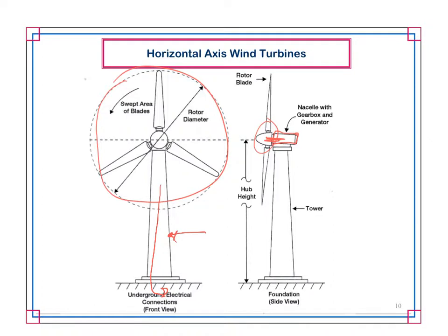So you've got some voltages, and it could be a transformer there, or it doesn't need to be, but you could have lots of low voltage cable or a little bit of medium voltage cable, and then it goes out, and then you run at least a couple hundred feet away, and then you would pop up above ground and then go overhead, because overhead construction for interconnecting electrical systems is much, much cheaper than an underground system.